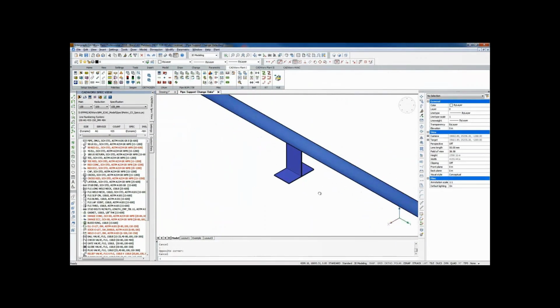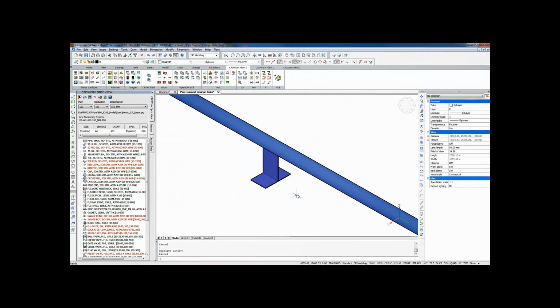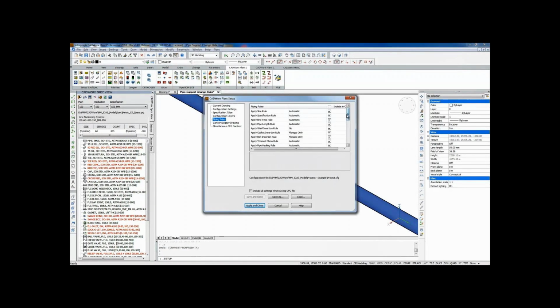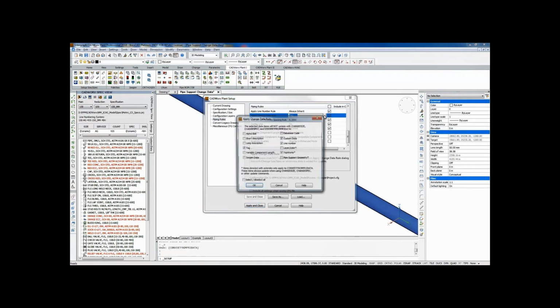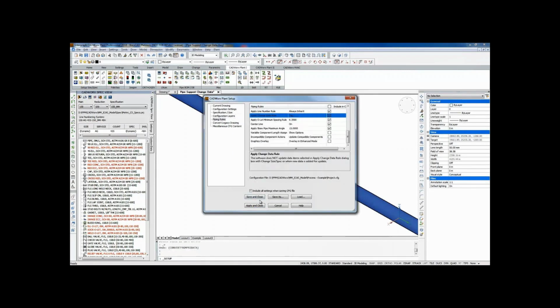Now in this, we have one pipe support placed. I'm going for the convert from project data here to change this. Now it gets updated with the size over here. Now going for this, and then applying this setting so as not to disturb or change any pipe support geometry with this, right?